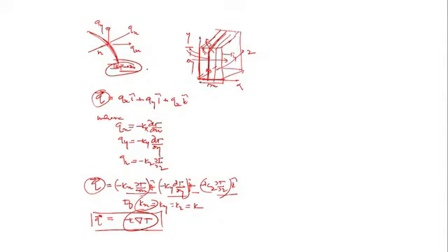The thickness in the x direction is very small, so any variation is found only in x. Is this clear? Any variation in y and z is very small and can be ignored. So by ignoring it, we simplify our problem as one dimensional heat conduction.